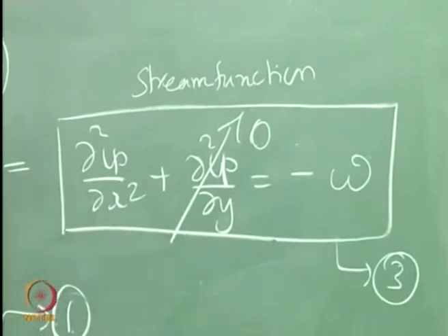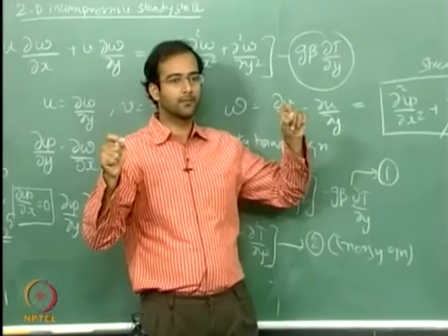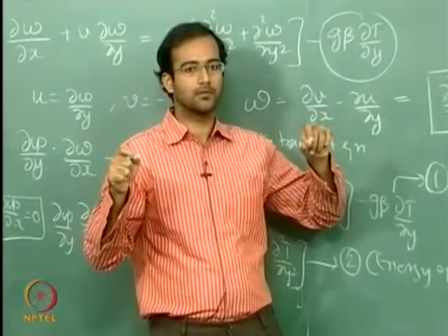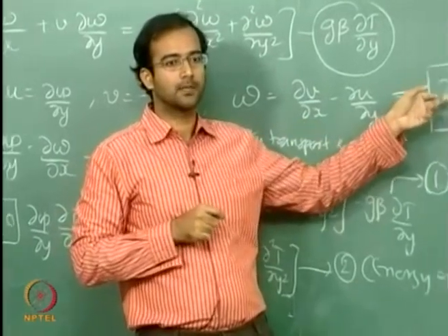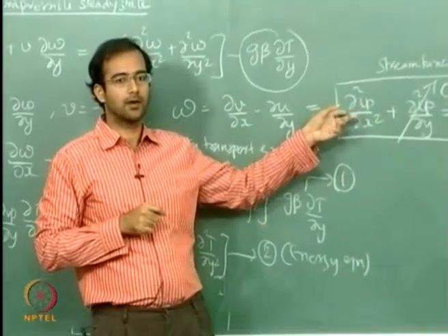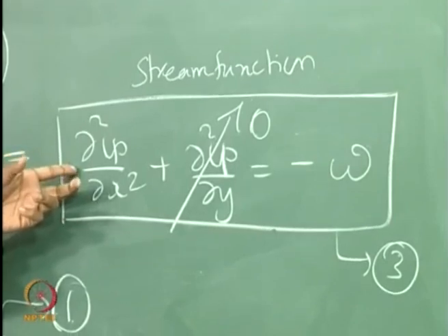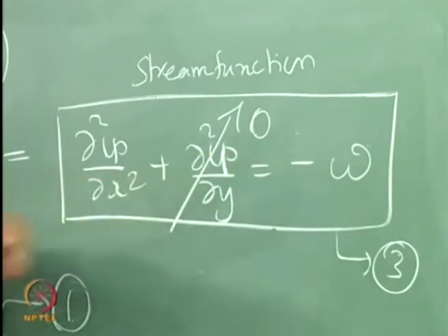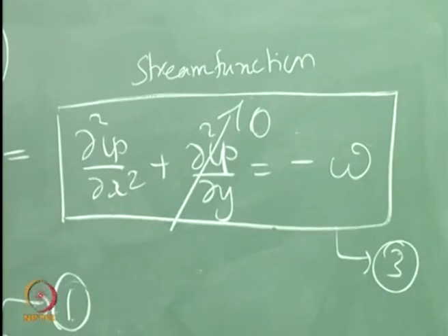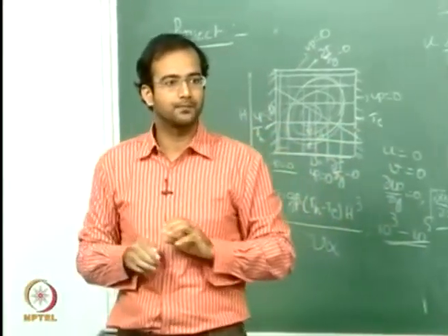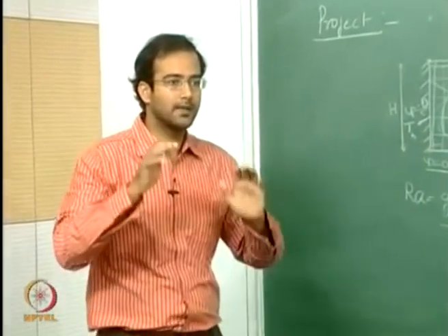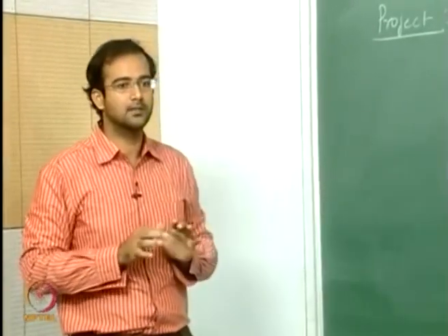You can write as simple Taylor series expression for the boundary in terms of the interior point, and you can express this in terms of the stream function at the boundary. So therefore you can directly calculate your vorticity at the boundaries. So all this is very clearly explained in the document. Okay, so you please read through the document. If you have any questions you can ask me.